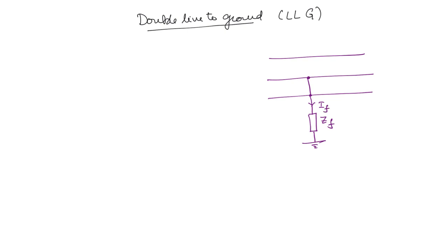The fault current. Okay. So, now if this current is IB, let us take this phase as A, B and C. So IA anyways it will become 0, and IB is here, IC is here. Okay. So you can see that IB and IC both will go towards the fault current. Okay. So one relation you can write here, IB plus IC, this is equal to the fault current.